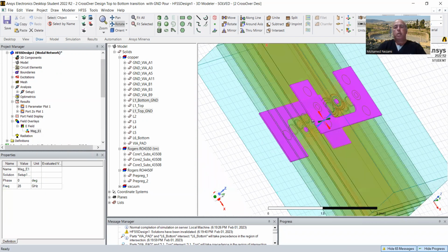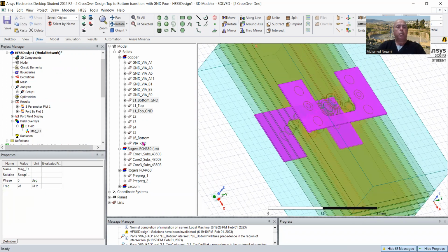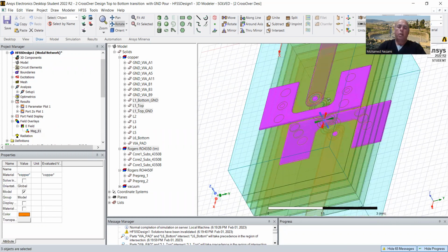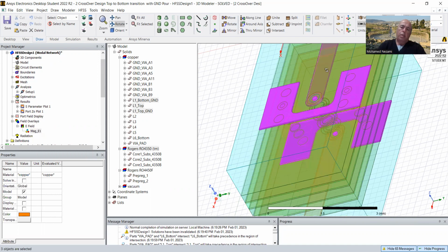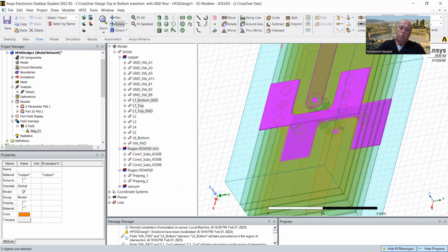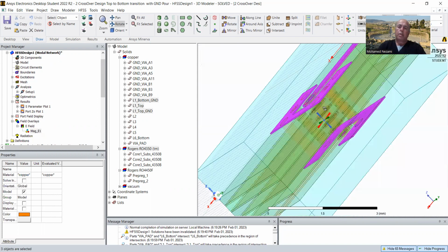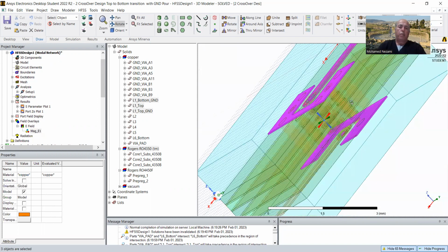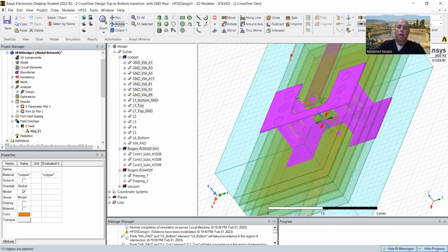Intuitively you think, well, the signal is coming this way and has to go over and cross. So I really want to make sure that it stops here, and any leakage would be grounded right there. And that's where you have these here and the vias that you see along the signal via.